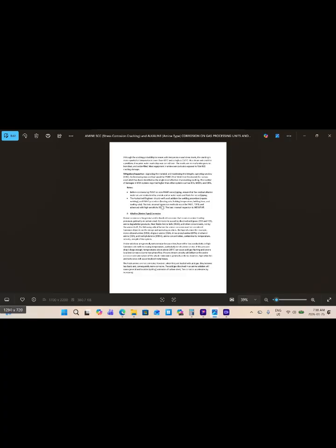One of the best methods is to avoid the temperature range between 40 C and 150 C, and all this cracking damage is reported at temperatures lower than 40 C and higher than 150 C. Between 40 and 150 C, this amine stress corrosion cracking is low,